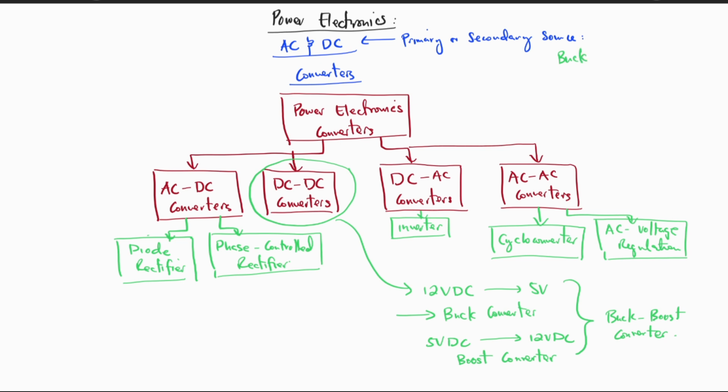And for the buck, imagine if we have a circuit board where the input to the circuit board is 9 volts, and we have some subsystems which use different voltage levels such as 6 volts, 5 volts, and 3 volts. In order to convert the 9 volts into the equivalent 6 volts, 5 volts, 3 volts, that means they have a lower value. A buck converter circuit is responsible for converting this higher voltage such as 9 volts into each of these voltages which is required by each of the subsystems inside an overall system.